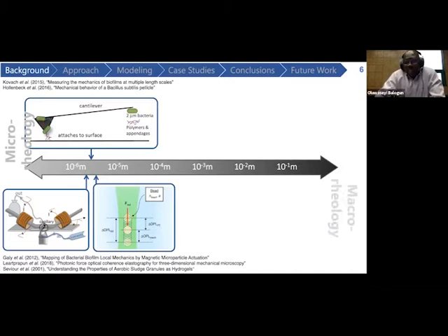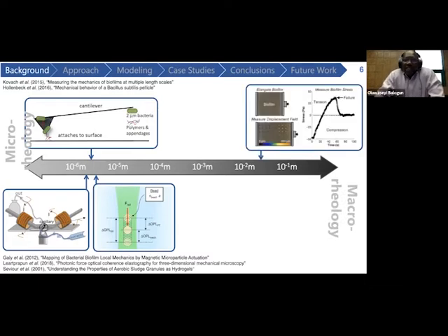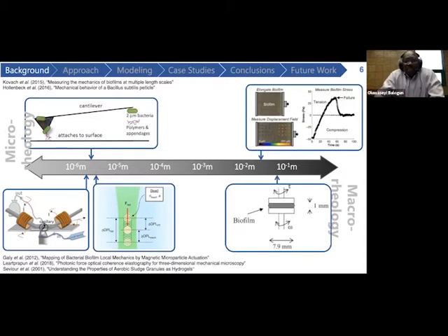On the larger, longer length scale, we have instrumented tensile testing that has been used to characterize the load displacement behavior. These methods can also be extended for creep testing. And also the famous rheology measurements have been applied. One of the challenges with the results from these methods is that they're completely different, and that's because of the high degree of heterogeneity of these biofilms.